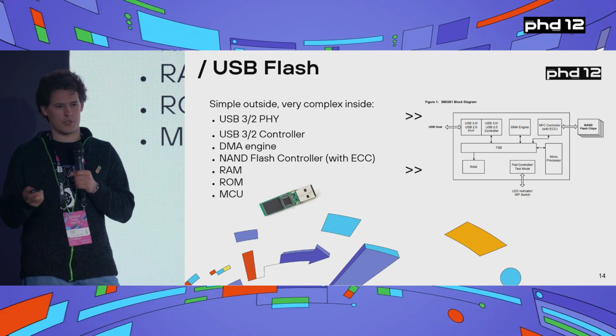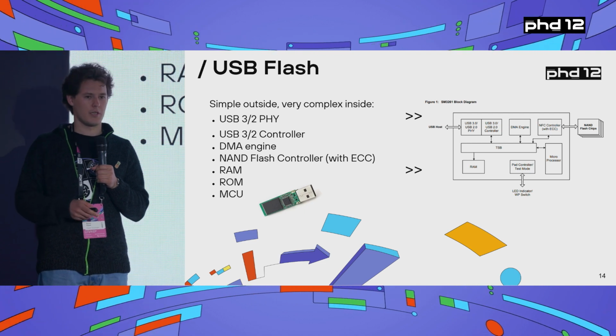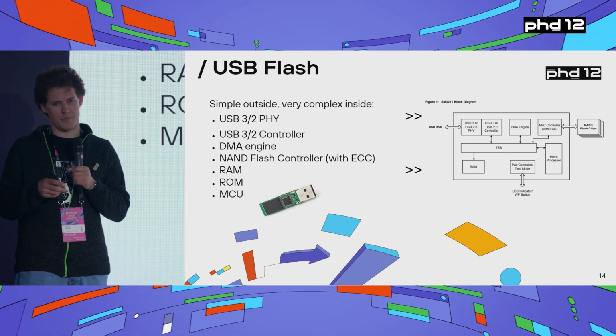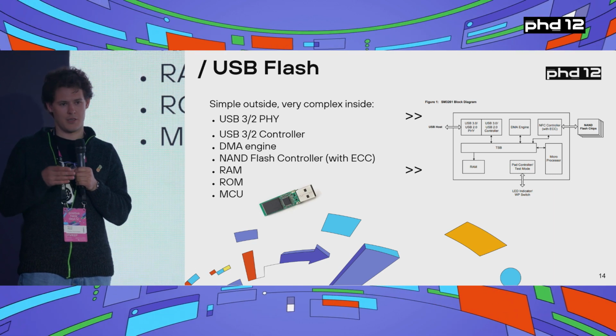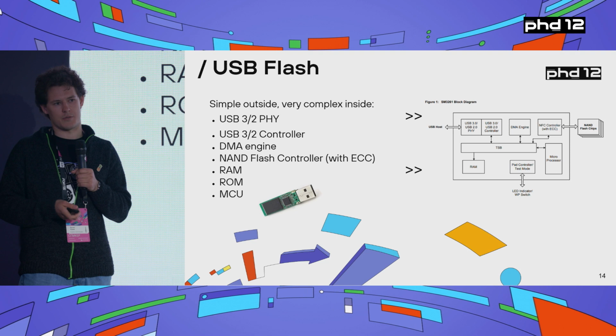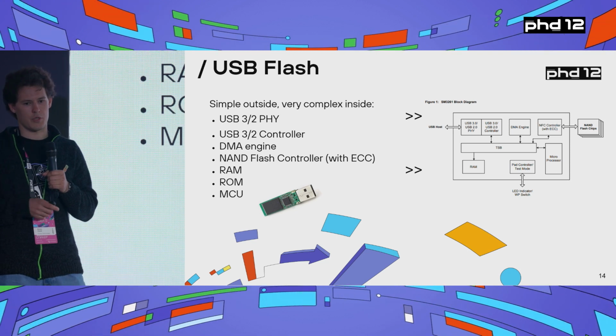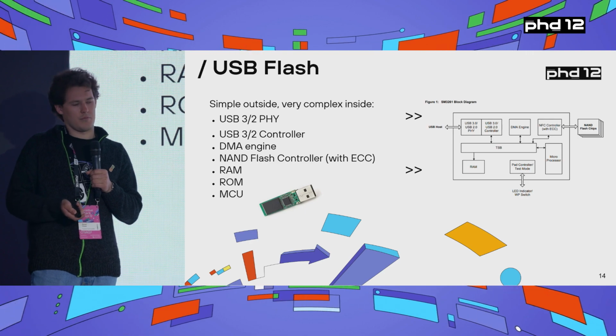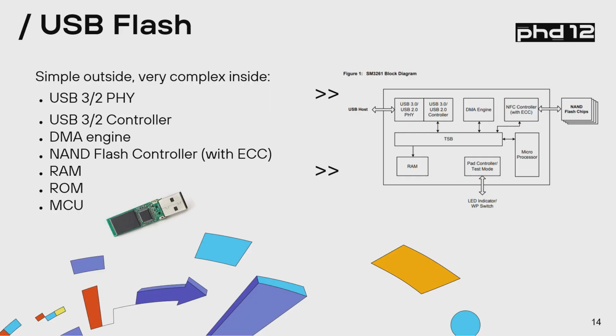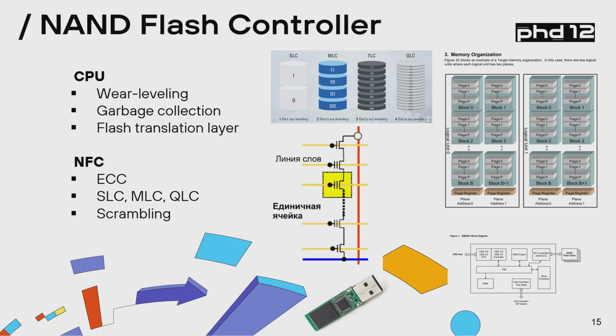I've already mentioned something about the NAND controller. Take DMA, for example. With DMA, you can mostly see it, right, because of the memcopy function. And you'll see some arguments such as source and receiver and size or volume, maybe some other simple settings. But the NAND controller is in a different league of complexity because there are lots and lots of functions which are embedded in the hardware, and you don't really see them happening at the software level.